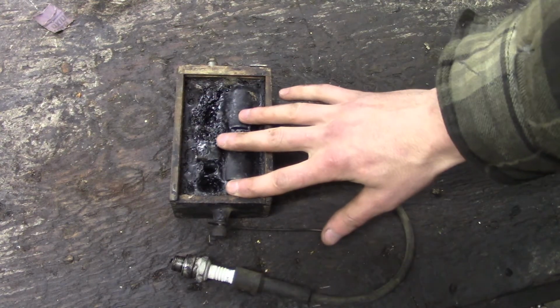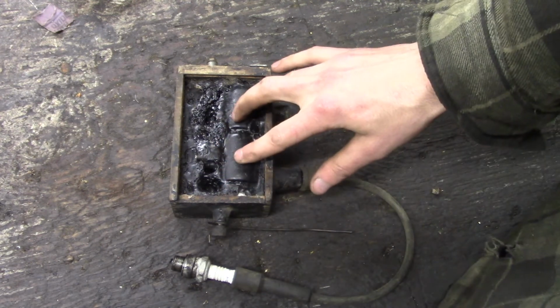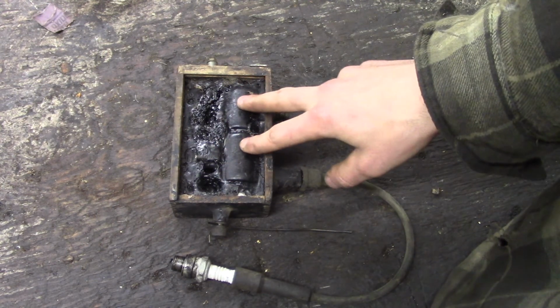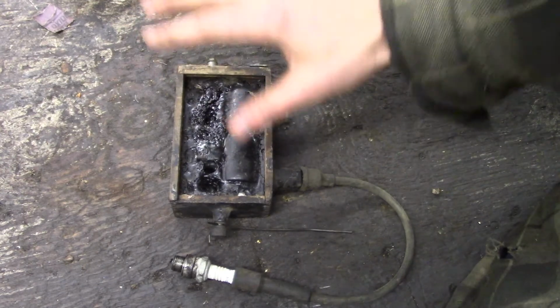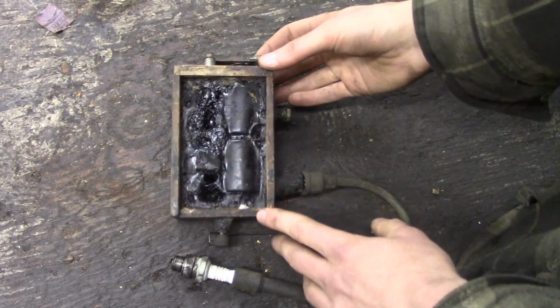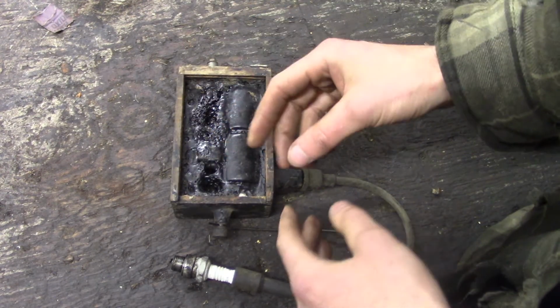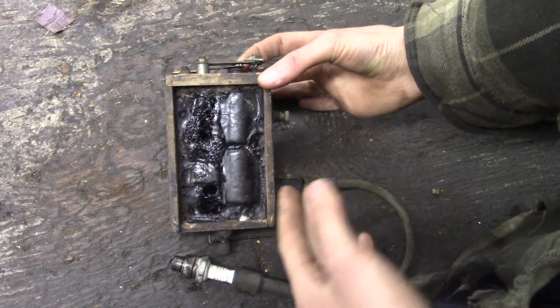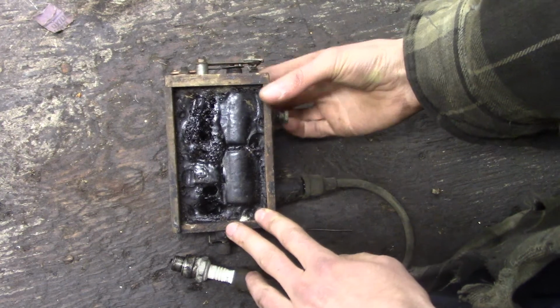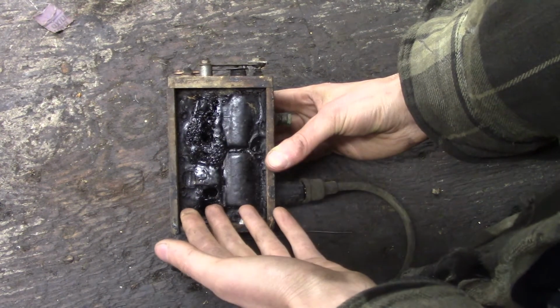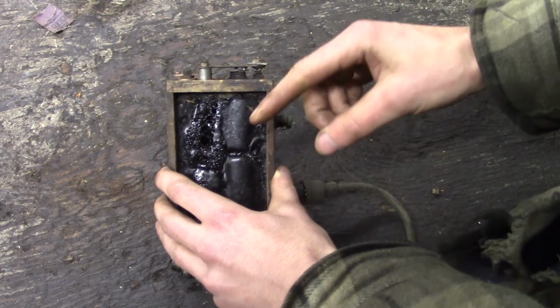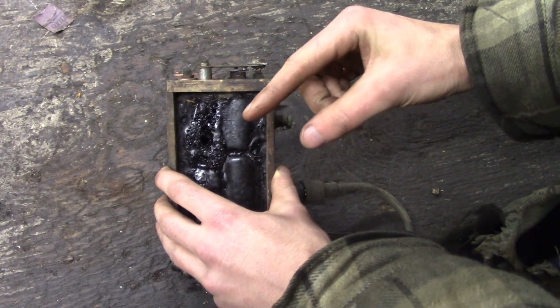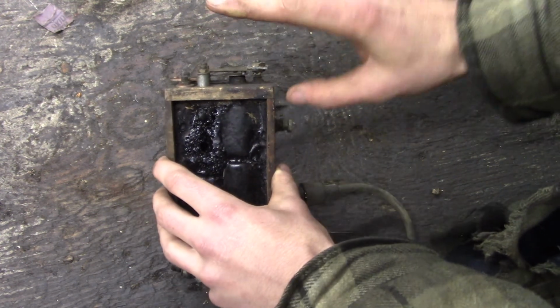So the buzz coil is also a little bit unique. It's a little bit different than the quick and dirty diagram that I drew for you, because this will also oscillate itself. It'll make a continuous spark. In something like an old car with a points ignition system, the points are opened once by the cam in the distributor, and that makes a spark. But in this case,